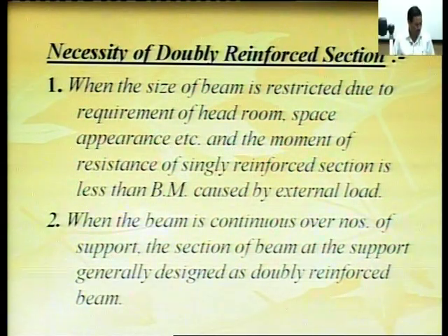So when there is a problem of headroom, space, appearance, and there is more load, we prefer to use doubly reinforced beam.